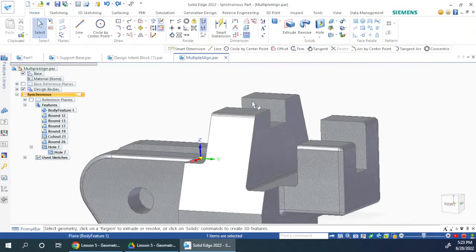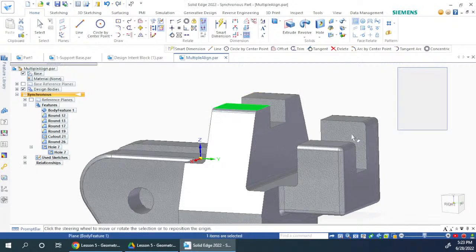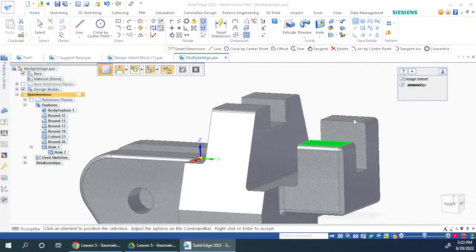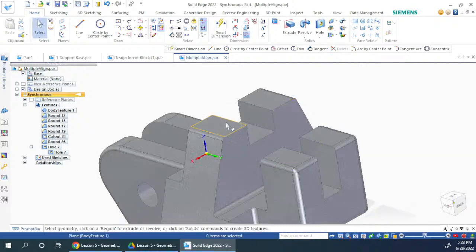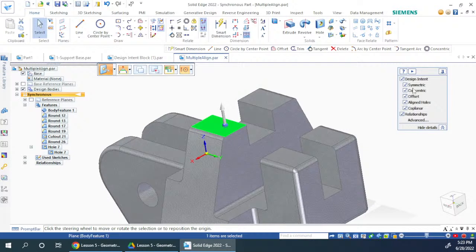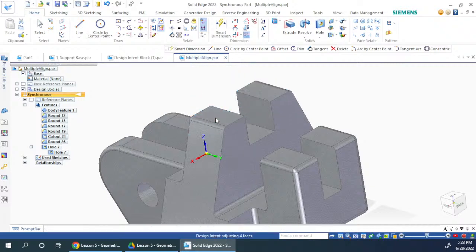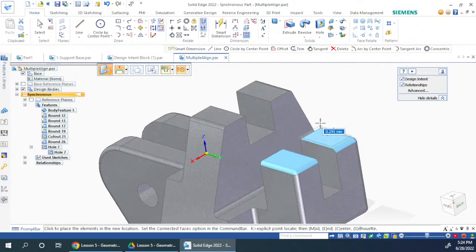So what I'll do is I'll just select this face, coplanar. I want to do single align with this, click OK, and then I want to move this plane, coplanar, single face of course, with this. Fine, so click OK. So now that both the faces are aligned, when I edit one of them by keeping coplanar design intent, both the faces which are in the same line will get modified. Getting it? Same way, if I'm moving just this one, this will get moved.